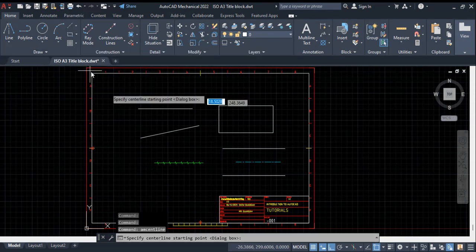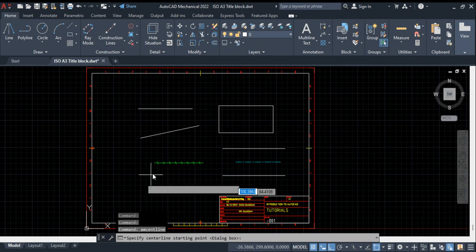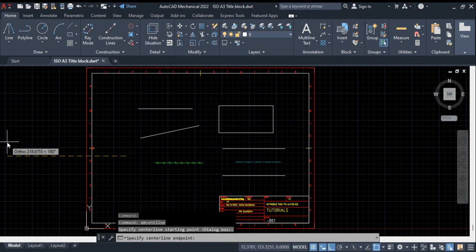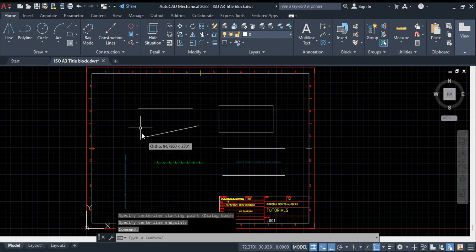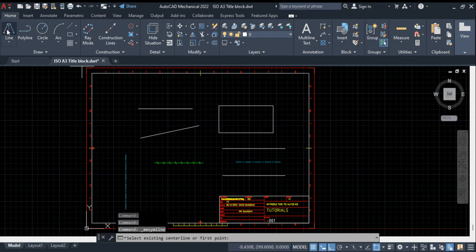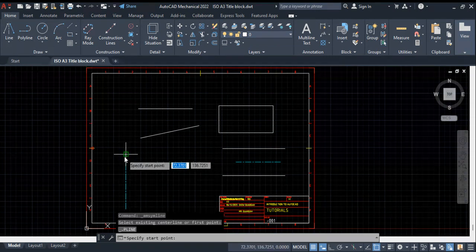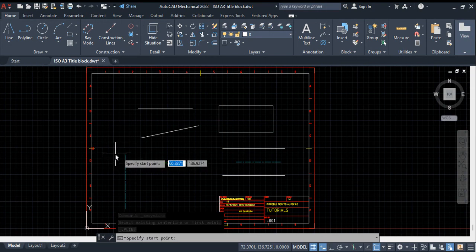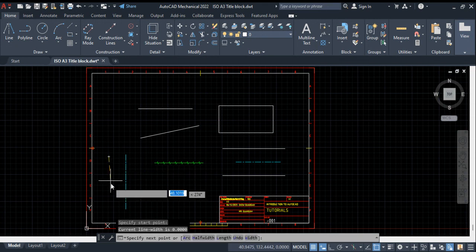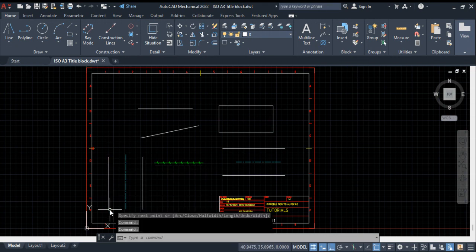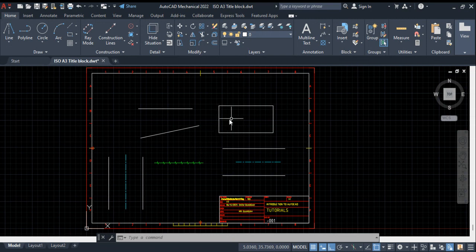Select the center line and let's draw a center line that is vertical. All right. Then let's go and select symmetric line. Then we select our existing point. Then let's try and create a symmetrical line here. So I click on that, press enter, and I've gotten a symmetrical line. So it's up to you for you to try your hands on it and then make sure you get to know how to use them.